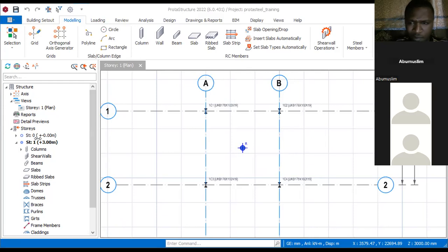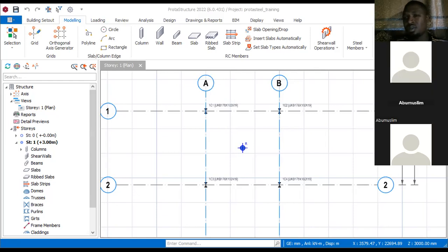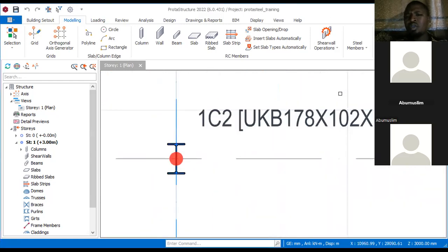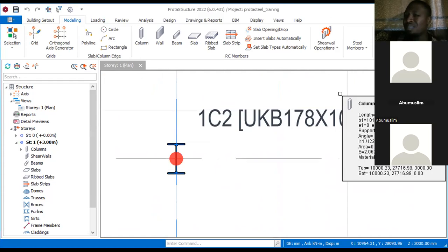From the point of selecting the column section. Okay. I started by saying that when picking a section, based on experience, you can be able to tell that this particular steel section will most likely serve. But in your design, you are designing based on trial and error. Now, you picking a steel section does not really mean that this particular steel column that I picked would definitely pass.